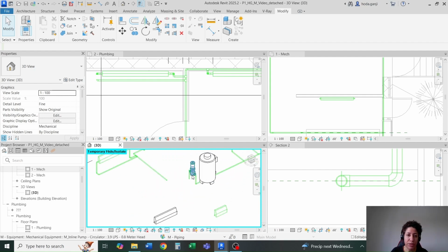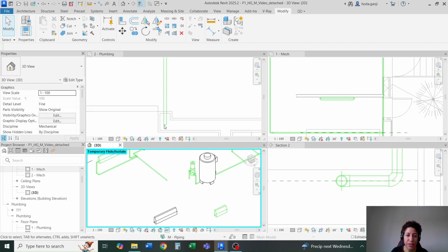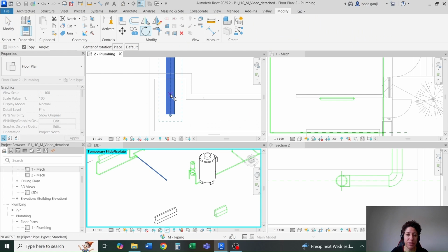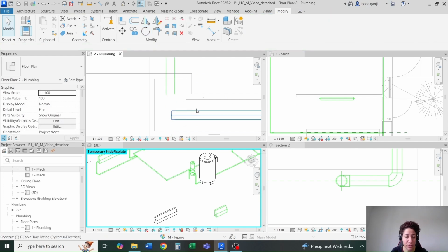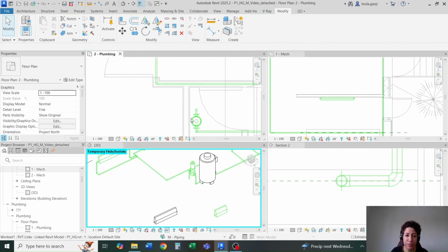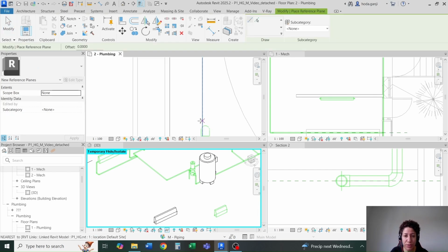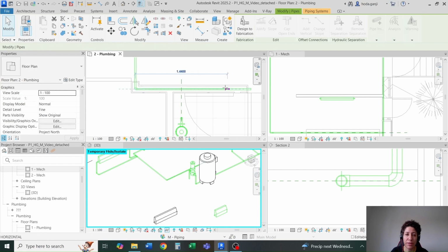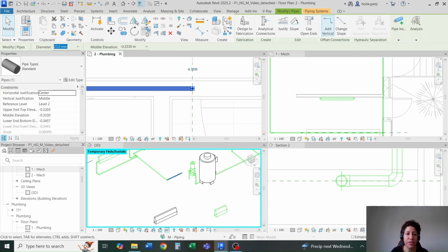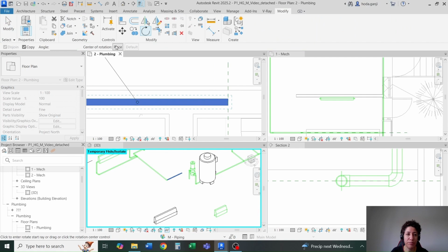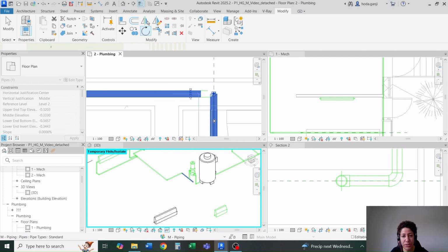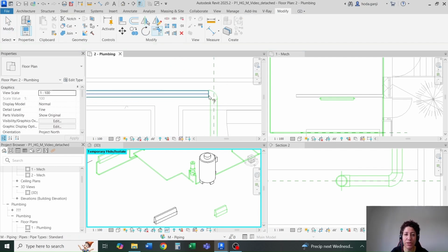And this needs to be a closed loop. So when it gets to here, I want to rotate it using place. I'm going to go with 90 degrees. I'll use TR, trim. And maybe I'll use one RP here to know where is the center line of this pipe. I can rotate this again using place, 90 degrees, and I'll go with another TR.